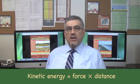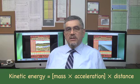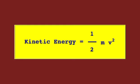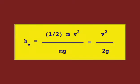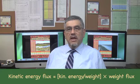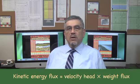The kinetic energy is equal to force times distance, that is, mass times acceleration times distance. It is expressed as follows, in which m is the mass of water. The velocity head is the kinetic energy per unit of weight. The kinetic energy flux is the kinetic energy per unit of weight times the weight flux. That is, the kinetic energy flux is equal to the velocity head times the weight flux.